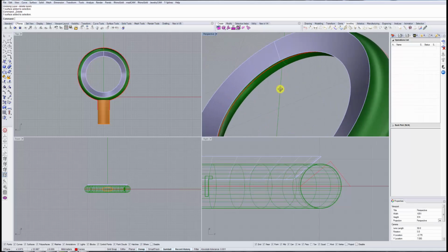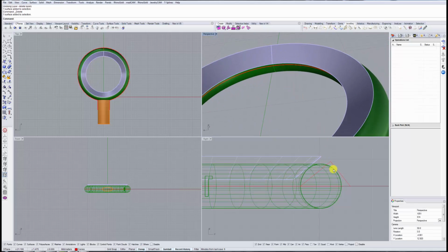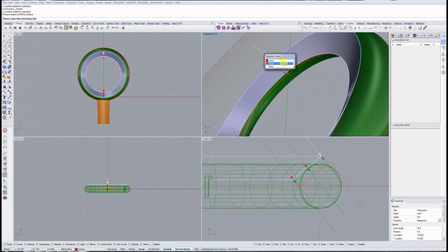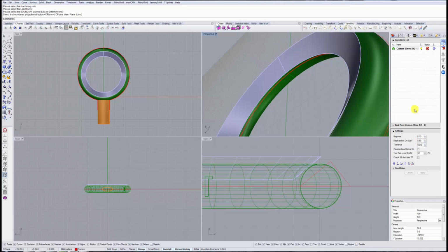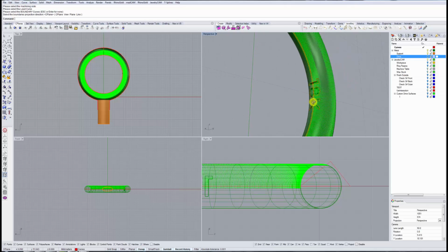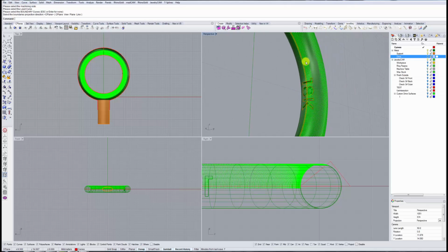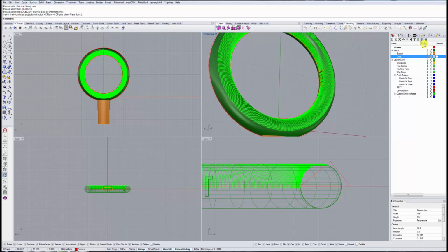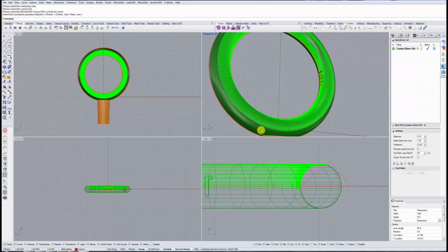So this was created using a simple sweep and a line. As you can see, we go to our drive surface option again, specify our direction, our lead curve, and we'll leave all the other options at default. Now I increase the step over size a little bit, simply to accelerate this calculation, but you get the same idea either way. Let's see what we have. Here we see now that our path is going this way, and it doesn't look all that unusual, with the exception of the fact that we're actually seeing something very powerful here, the full 5 axes of work.